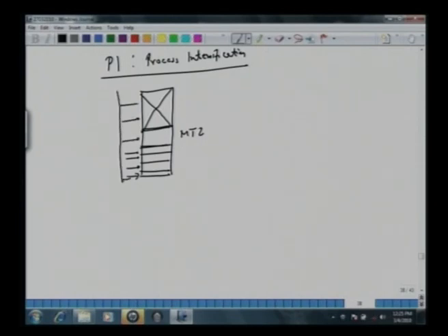All right, this is one example of process intensification where you put some valves in each of these streams, and as the wave propagates, the feed can also be moved upward, up to this front, so that at any time whatever feed is brought, it's brought in contact with the mass transfer zone. In other words, if you have the feed here and this bed is saturated, then the entire feed has to elute. There is elution, so essentially this is ineffective. This is a zone where nothing happens.